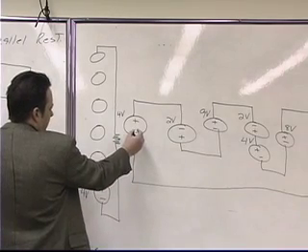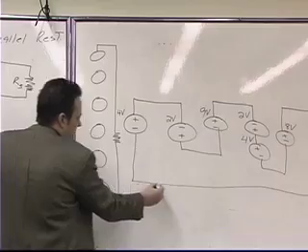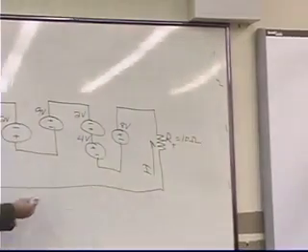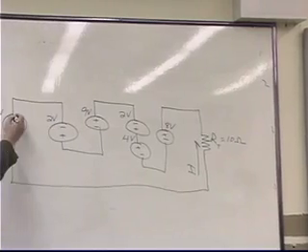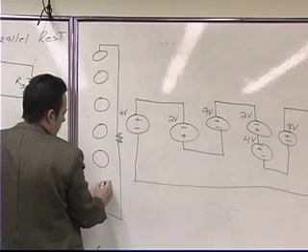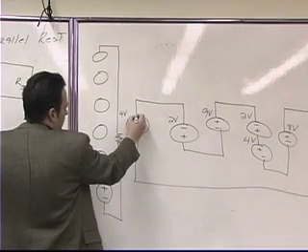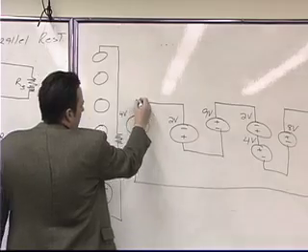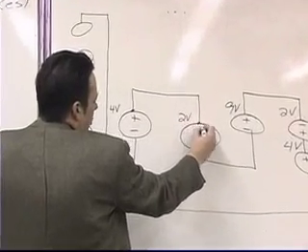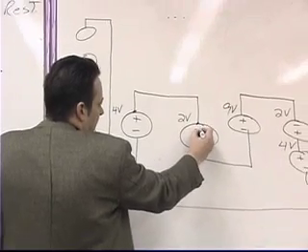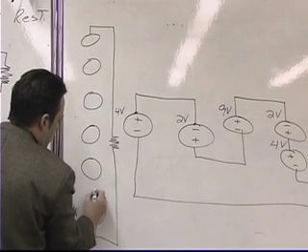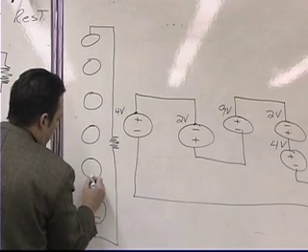You notice here that this negative terminal is connected over to the load. So then I'm going to follow this positive terminal, which is the point where I am right now, over to my next battery, and see what polarity I come into. Is it negative or positive? It's negative. So I'm going to draw a straight line up to this point right here and then put a negative.